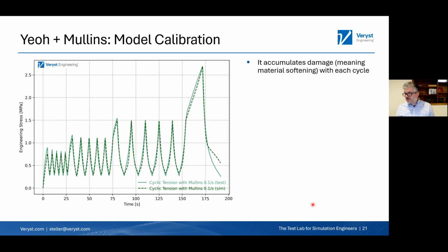Would these models lend themselves well to rotational cycling, as in rolling contact fatigue? I don't see why not. I don't know what particular model you're talking about, but the LVE or the nonlinear Bergstrom-Boyce or the three network models should all capture that fine.